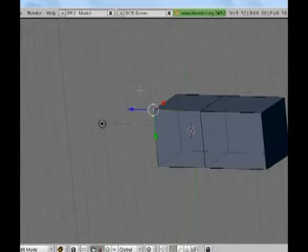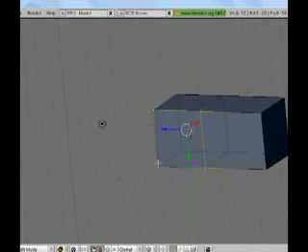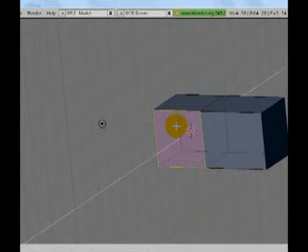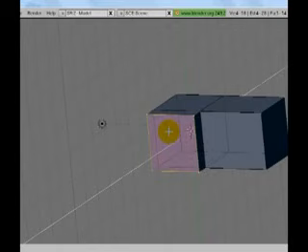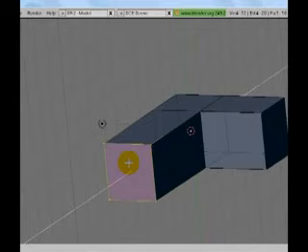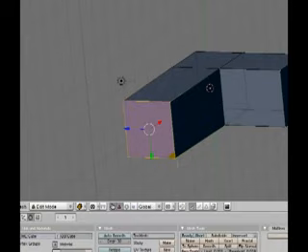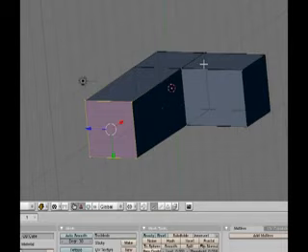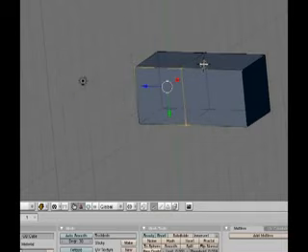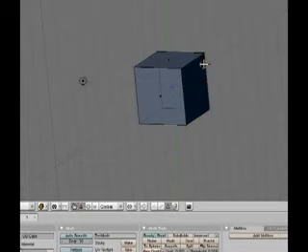And if you're already in vertice mode, you can extrude a whole face. If you hold in Shift and right-click on vertices, it allows you to pick more than one. And now if I extrude, I had to pick region right there. It'll extrude the face because these 4 vertices make this face. Okay, so I'm going to Control Z just to get us back to the first cube.